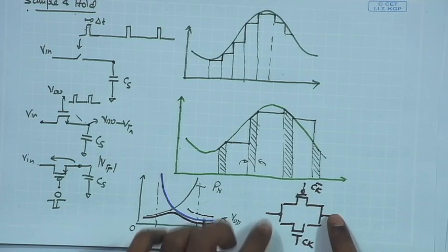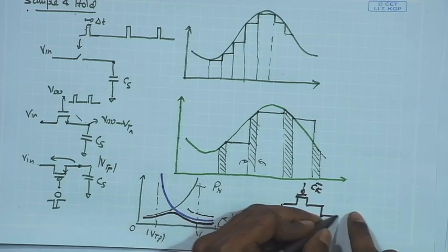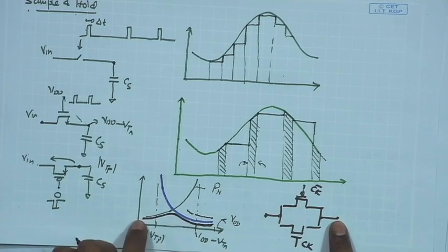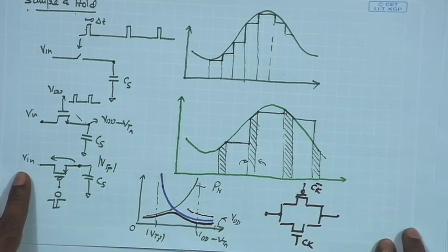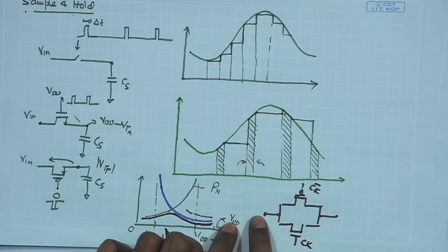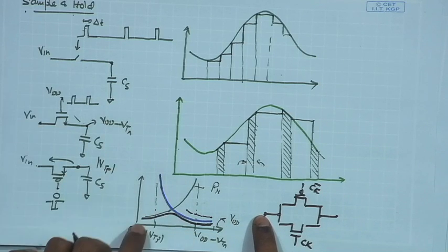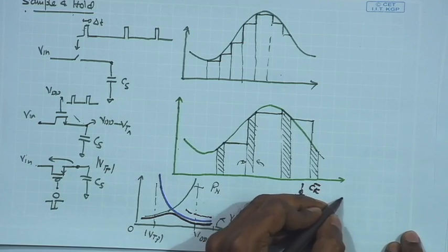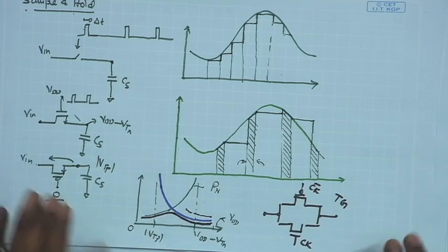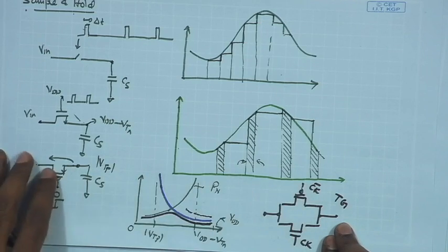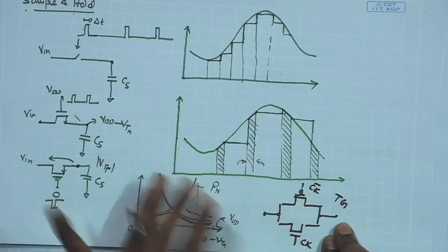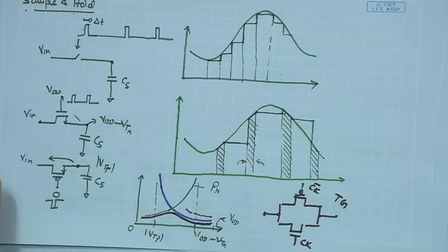In this case you can have an overall resistance across the switch which remains relatively flat across the entire input range, and it can sample an input signal going all the way from 0 to VDD. So, this is termed a transmission gate, which is very effective in sampling operations or analog circuits where we have constant sampling of analog data.